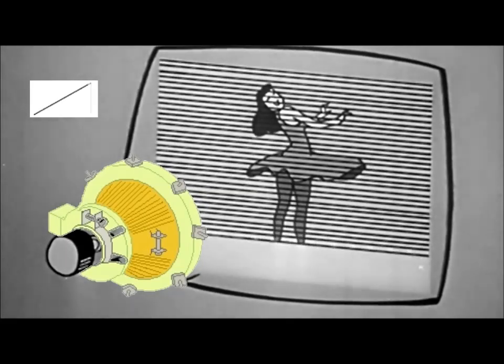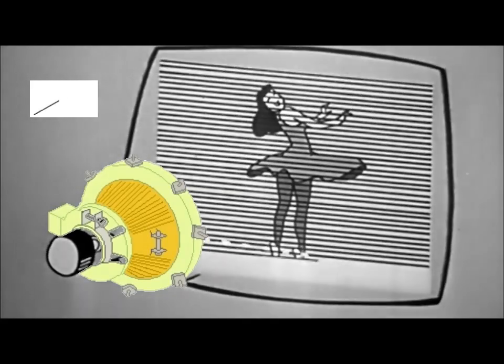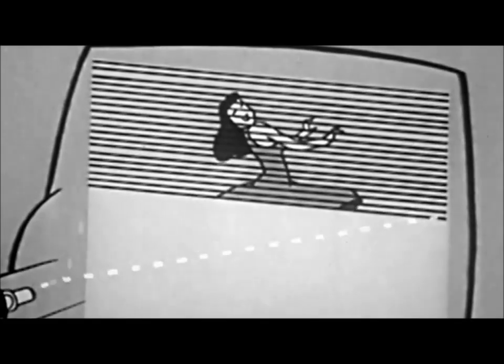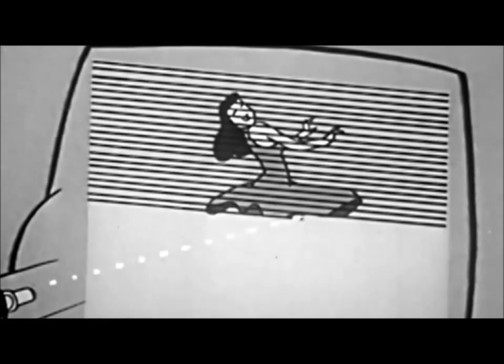The camera has to tell the monitor where there is a dark or light portion of a picture, but it also has to tell the monitor when to start and stop producing each line of video, and also when to begin and end each field as well. That's the purpose of synchronizing signals. A group of special signals are sent by the camera to pass along this synchronizing information.